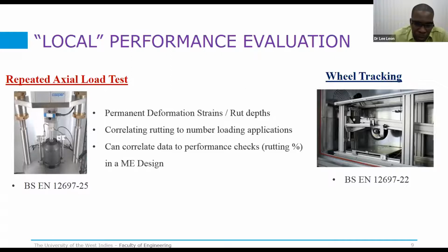Now, both will give you the permanent deformation strains or the rutting depths after a number of loading cycles. Now, this test can be done at varying temperatures, so we can actually run this test at ambient temperatures or higher pavement temperatures, which we experience in the Caribbean region.